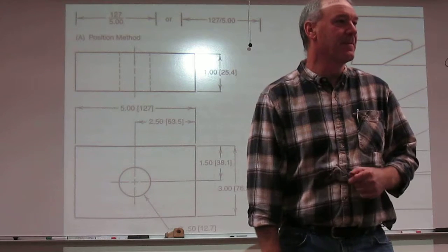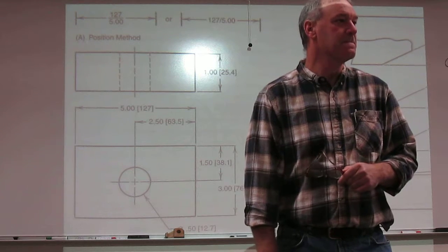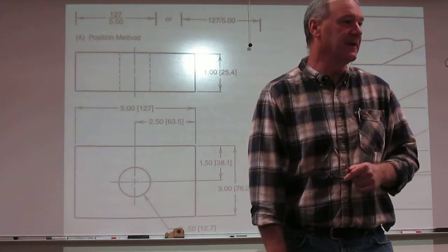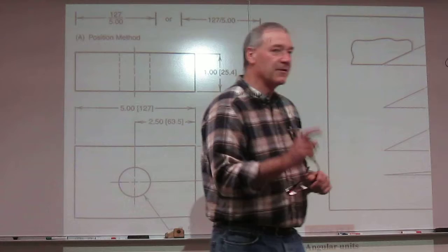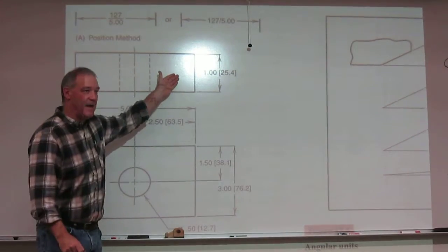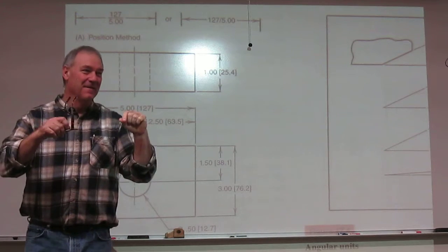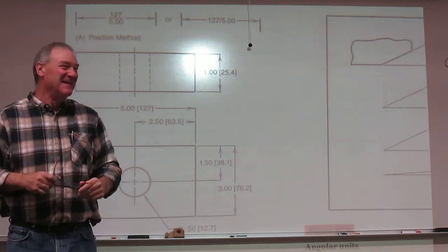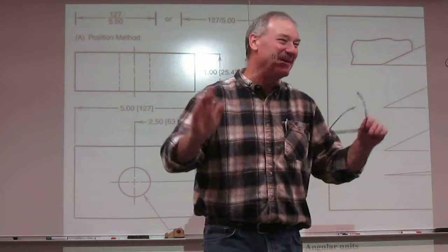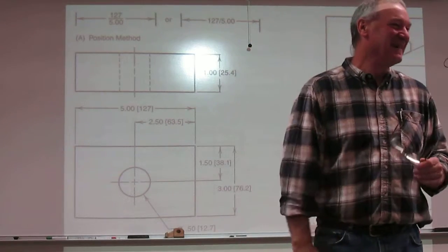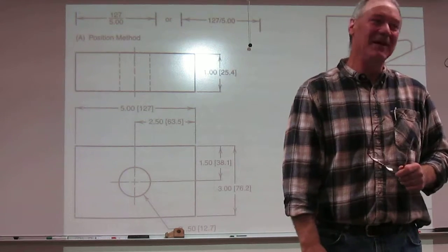Does having it dual mitigate some of that? Yes, it does some of that, because you've given them both of them, so they don't have to pull that calculator out and figure that number. And if you draw a true size in the computer, we're not going to do this by hand, but you draw this in the computer 1-to-1, that's why we keep that geometry 1-to-1. They keep telling you folks, if you get a desire to scale that geometry, slap yourself and say, don't do it. This is another reason why. Because the computer is really a Cartesian grid and we can get it exact and it won't make mistakes.